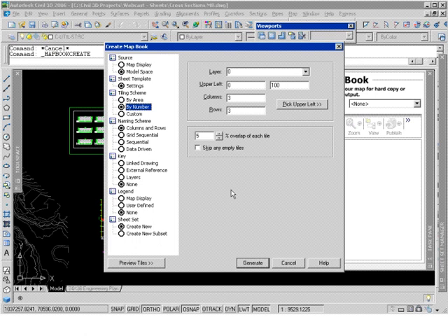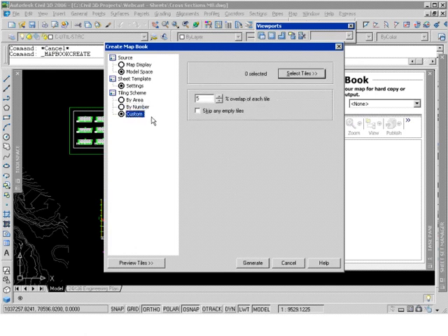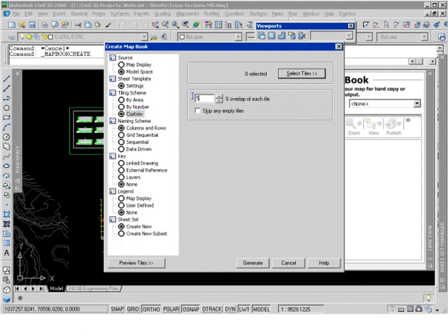Do I just have a number? And if I know that I want to work with a grid that's 10 by 10, I'll go ahead in here and set the columns to 10, the rows to 10, and just give it a starting point to lay those out. And then there's custom, which is the one we're going to take advantage of here as a civil engineer,